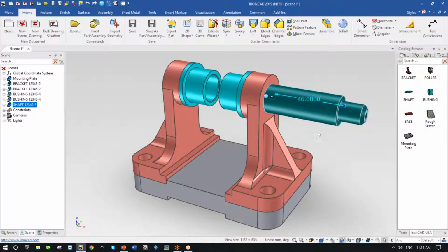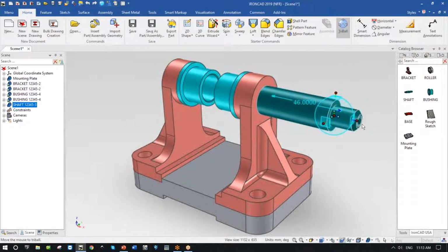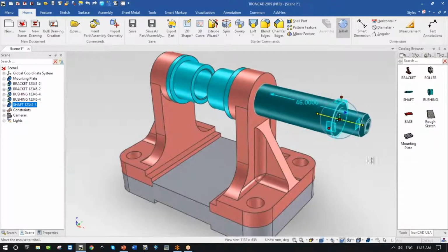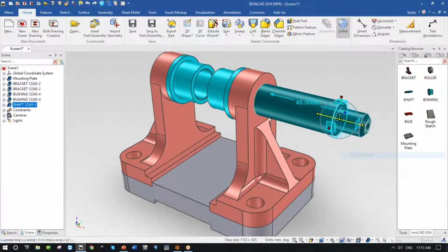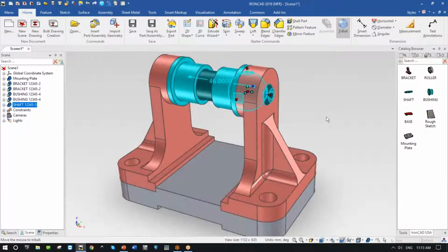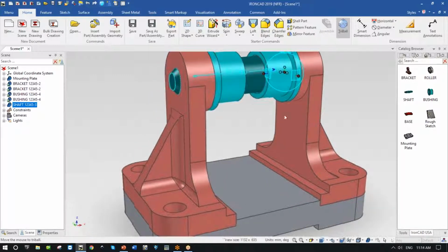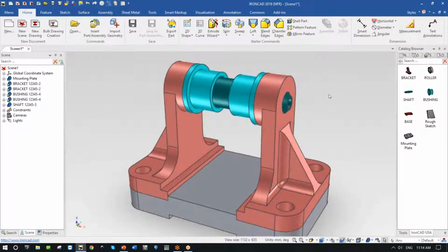And that's not quite far enough along, so I need to put it into position, but I want to control it. It's exactly on the center line. So I'm locking the center line and saying with the tri-ball, move this to the center point of this geometry. Now I can check my work and look, absolutely, it's equidistant there. So you're seeing how easy it is now.